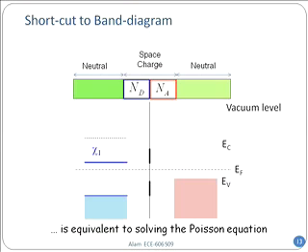Now, correspondingly, on the P side, I'll have to do this. First, I have to draw the valence band. Do you realize why? Because it's P region. I can immediately get where the valence band is. Now, I also know the band gap for this material. And if I know the band gap, then I can draw the conduction band, because that's separated by that amount. Next, for that material, whatever it is, I can also draw the vacuum level, because vacuum level is a property of a material. You open your textbook or any reference book, they will tell you for germanium what is the vacuum level, for silicon what is the vacuum level. So you just read it off from a textbook or from a reference book.